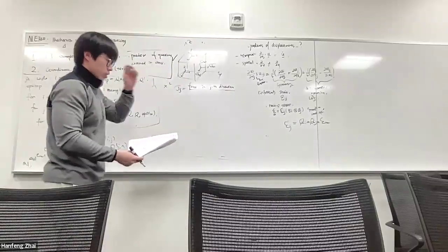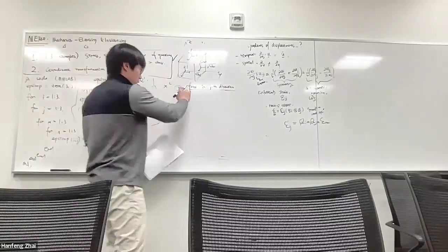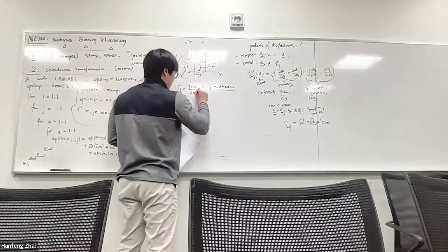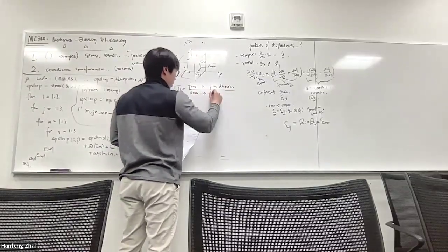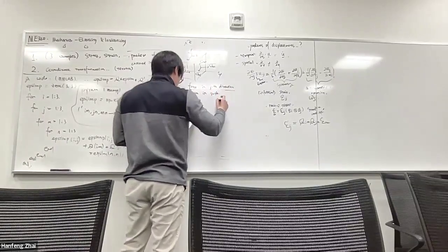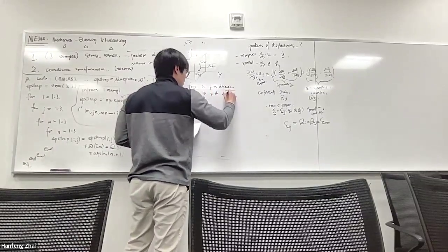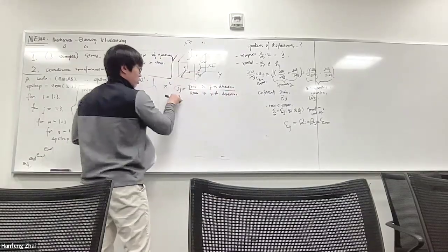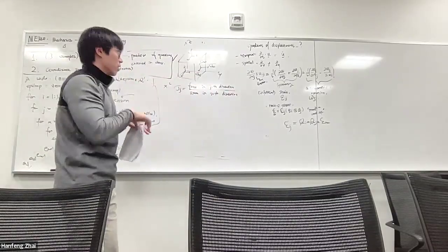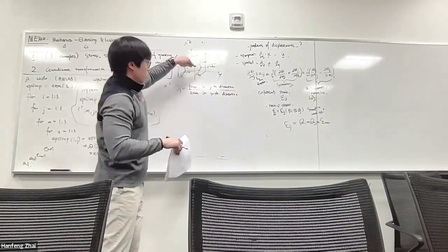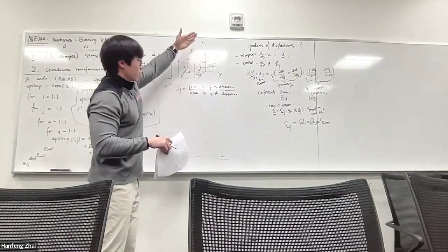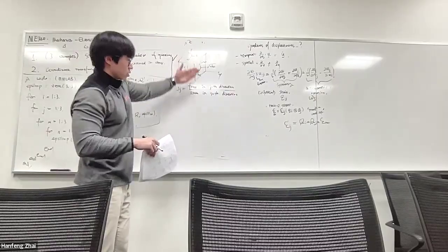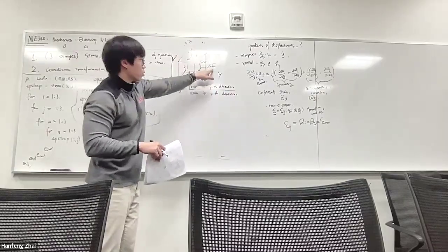And previously, we defined stress as force over area. The denominator is the area in the i direction, which means the surface that this stress tensor component is lying on. For example, this stress tensor component is lying on the y surface, or the 2 surface. That's why it's 2,2.